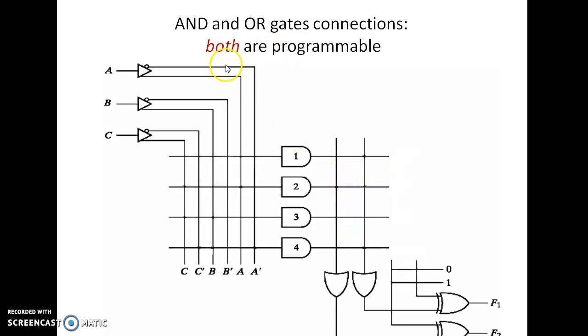So this is the typical PLA architecture where there would be a single line. This line would be connected to all the terms whenever it is required. And there would be a single line for OR gate which can be connected to all the AND gates. So wherever the connection is required, you put a cross mark. That is a PLA. And what are these XOR gates? These are the additional circuit, right? We'll be using. Why we'll be using XOR gates we'll be discussing later.